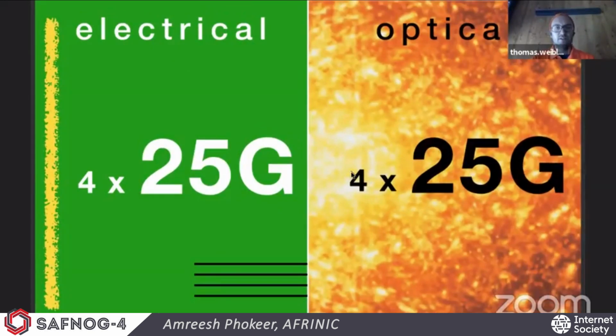So, you know, it's 100 gigabit we are talking about, so we start on the left side now. Open up a 100 gigabit transceiver. We see 2 main components in there. On the left side, you see the electrical components, having there 4 times 25 gigabit connecting to the optical side on the right side, also with 4 times 25 gigabit. This is basically the setup of today's 100 gigabit transceivers.